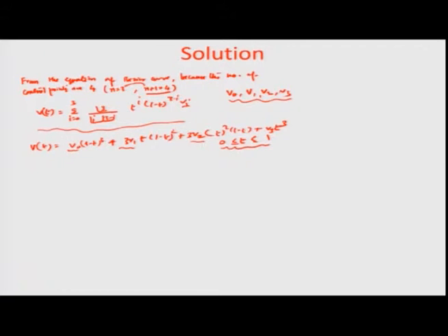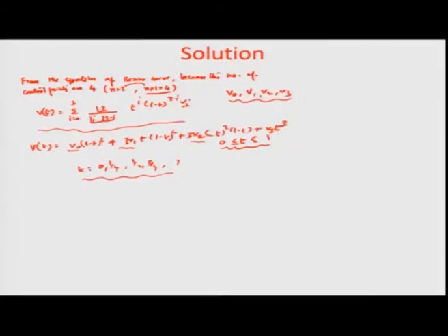So, when we substitute the x, y and z values, and the different values of t that have been given in the question, namely 0, 1/4, half, 3/4 and 1, we want to find out the different points of this Bezier curve. This will give you an idea of what points the curve would pass through in space, where the first and the last points are the same as V 0 and V 3, but the in-between points may typically be different from the control points. So, let us numerically try to solve this example here.